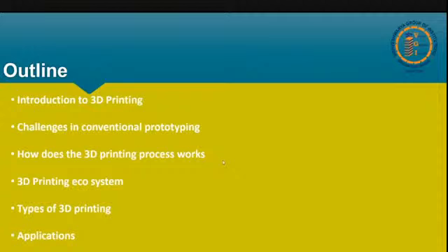The third, to counter the limitations of the subtractive and formative processes, is additive manufacturing, which is basically 3D printing. In additive manufacturing, we don't have to subtract anything from the material. We start laying layers one on top of another to make the part. In subtractive, there is a block of material and we are removing from it, so that's why it is called subtractive. But in additive, there is nothing at the start; we just put the layers on top of each other.